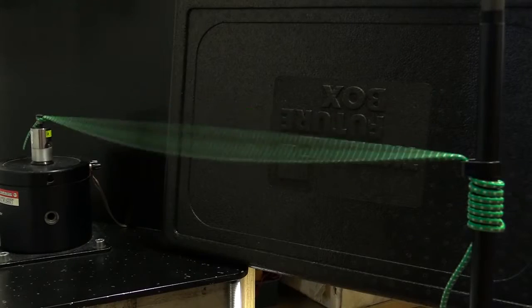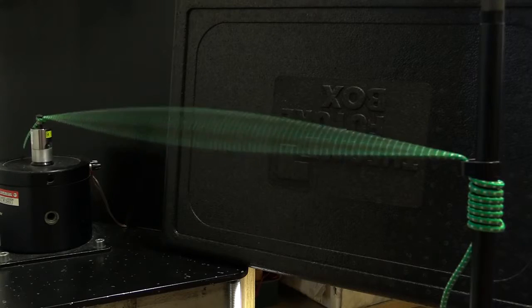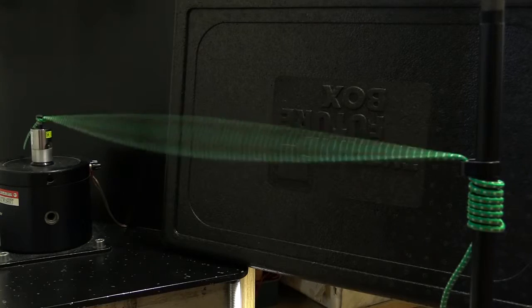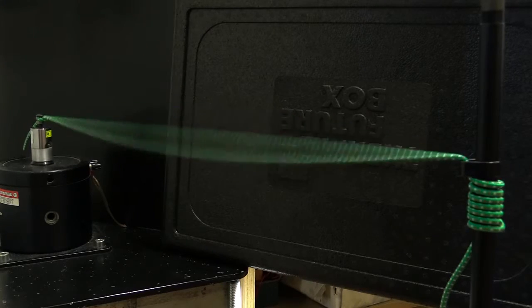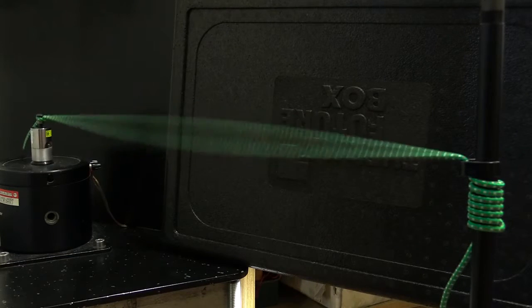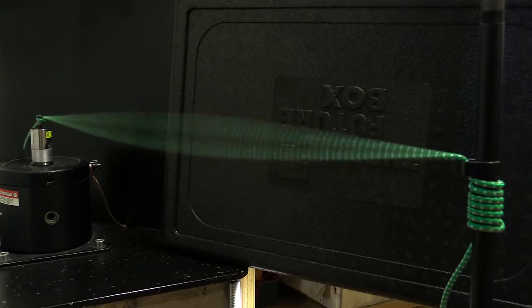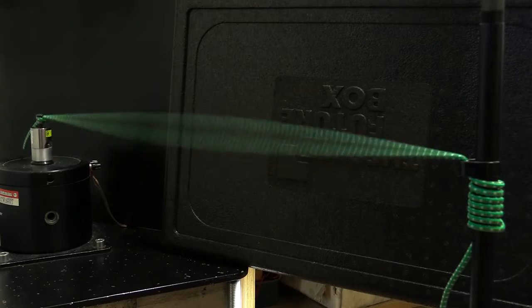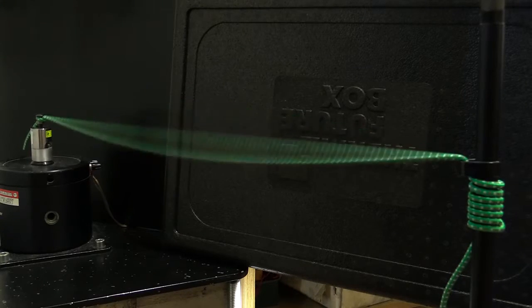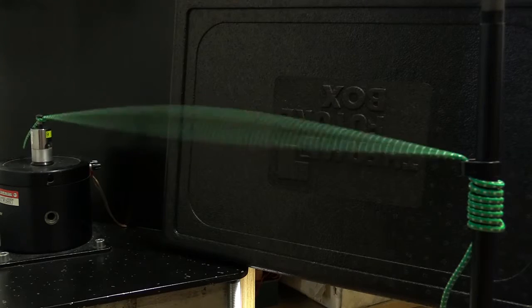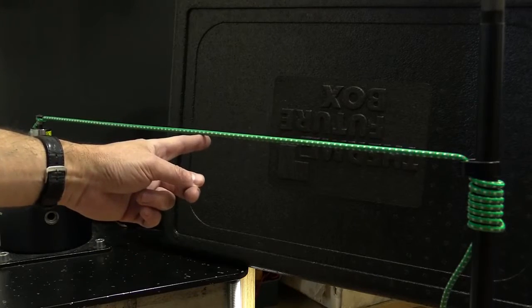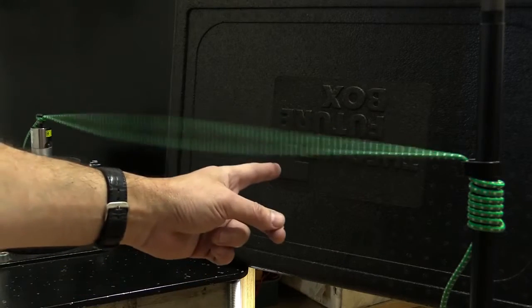In the next example, I show you why it is important to know the mode shape, which is the cause of the vibration problem. I use the shaker and the rubber beam. The first natural frequency is 10 Hz, and you can see the first mode shape. If I need to decrease the vibration level, then I can add the pillar to many places and it will work. You can see that the vibration disappears when I add the pillar here or here.